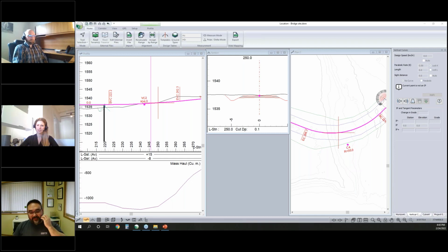The other thing is understanding what's underneath that, because sometimes it's not just excavating that weak layer, but once you open up the layer below, you're getting into more trouble. So then the other piece is, even if you've got a long haul distance and you think you can reduce the haul by excavating and replacing, you have to consider now you're hauling that material away.